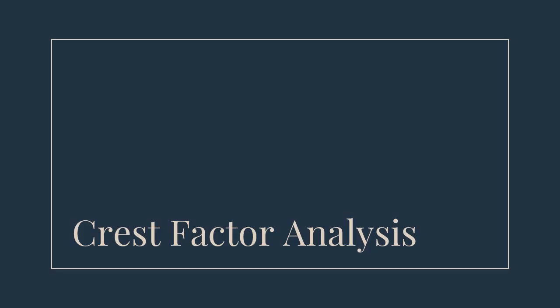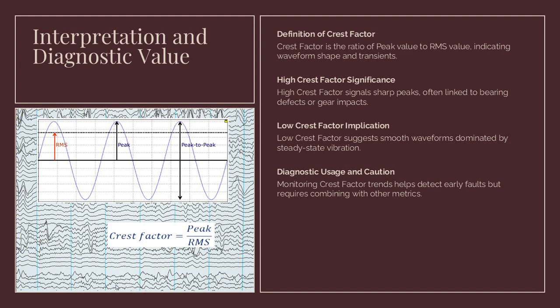Interpretation and diagnostic value: crest factor analysis. Crest factor is defined as the ratio of peak value to RMS value. It provides insight into the shape of the waveform and the presence of transient events. A high crest factor indicates that the signal has sharp peaks relative to its overall energy, which is common in cases of bearing defects or gear impacts.